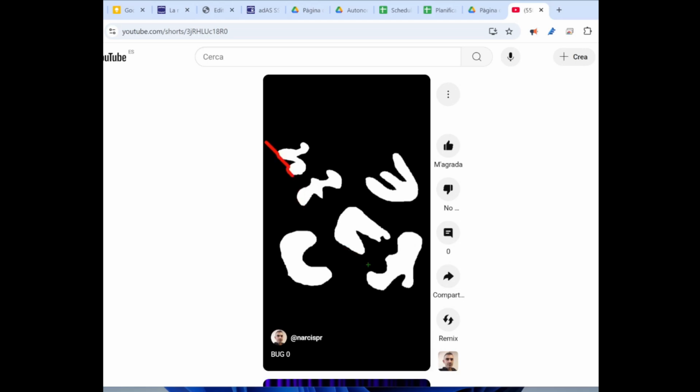This is something that the algorithm has to decide a priori, okay? And you cannot swap, now left, now right, no, because then you can end up in some local minima very easily. If you turn right, you always turn right. If you turn left, you always turn left. Then it just moves straight towards the goal. As soon as it detects an obstacle, in this case, it turns right.